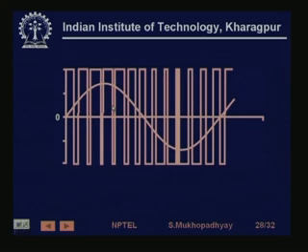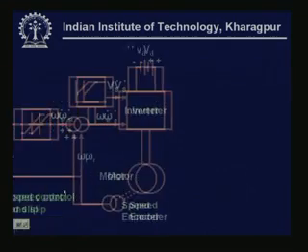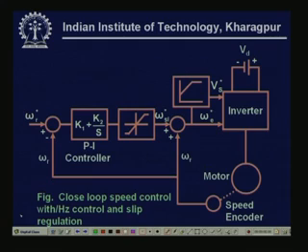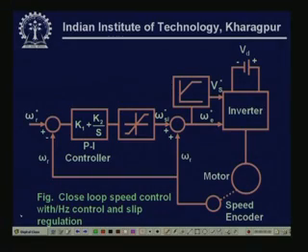So this shows that if you have a PWM switched wave like this, then its Fourier transform will generate an AC wave. It will generate a fundamental like this, and its harmonic content will also be improved over the square wave VSI, in the sense that lower frequency harmonics will not be present. So now we have seen how we can vary voltages and frequencies. Now if you want to implement a variable voltage, variable frequency control loop, so what happens is